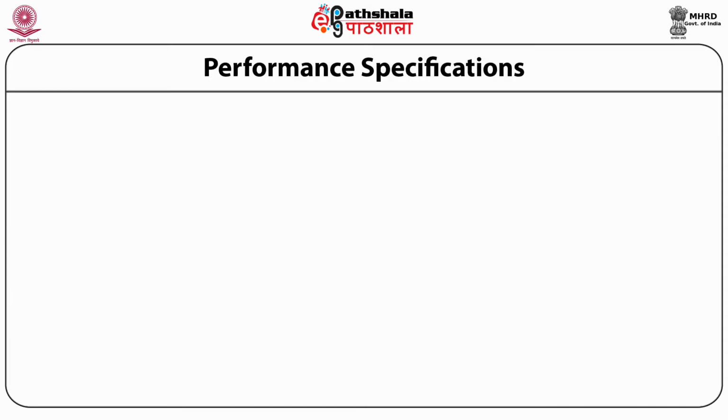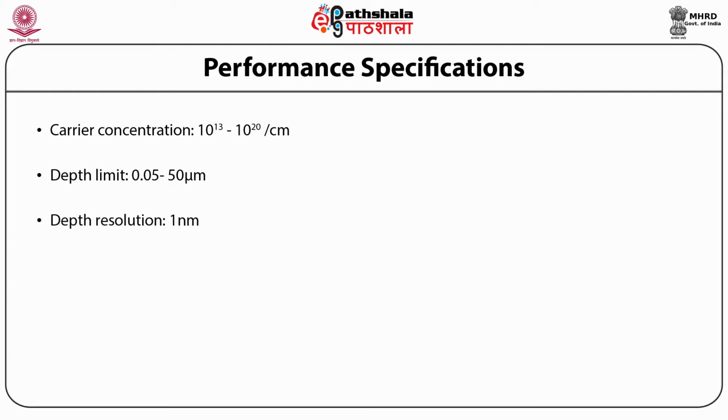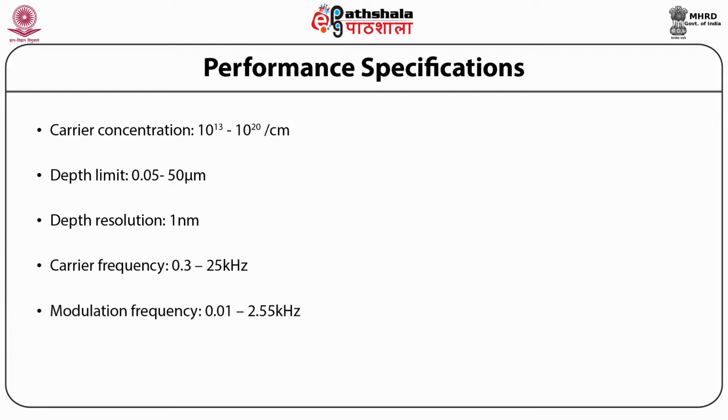Performance specifications: carrier concentration is 10 raised to power 13 to 10 raised to power 20 per centimeter cube. Depth limit is between 0.05 to 50 micrometer. Depth resolution is 1 nanometer. Carrier frequency is between 0.3 to 25 kilohertz, and the modulation frequency is between 0.01 to 2.55 kilohertz.